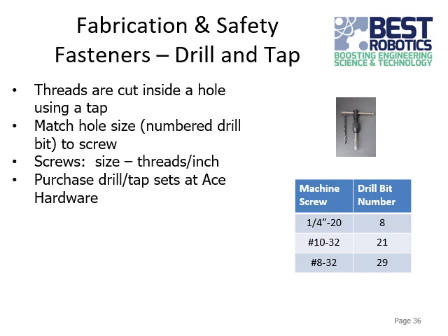So for fasteners, I'm talking about screws here mostly. A lot of times it makes sense to pre-drill screw holes in your wood and stuff like that, so you don't split it. But if you want to tap a hole, then you have to be particular about getting the right drill size and the right tap to match the screw.